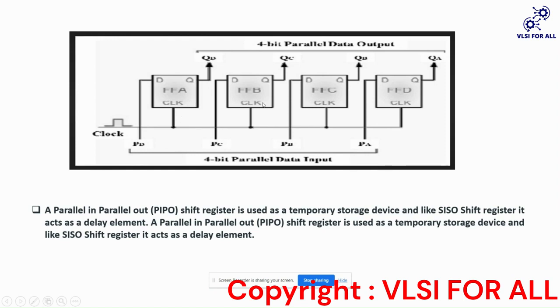That means the flip-flops do not have connections between them. Each flip-flop is individually connected to an input and the output is taken individually. For 4 flip-flops we have 4 inputs and 4 outputs. This means we give the inputs in parallel and take the outputs in parallel. That's why this is called a parallel input, parallel output shift register.